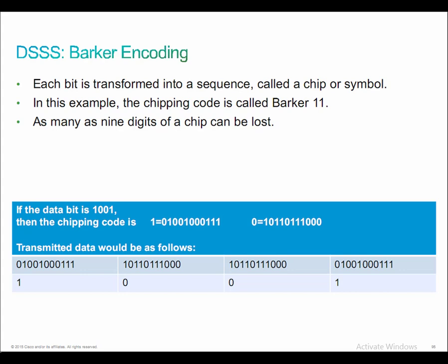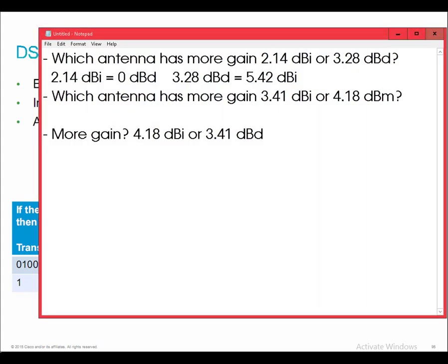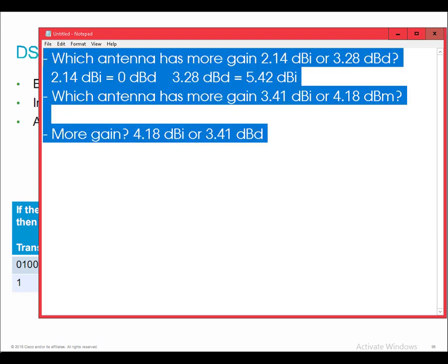Each digit of information that gets sent is run with something called an exclusive OR operation against this Barker code 11. Now, XOR operations, let me pull that up real quick. Boolean XOR operation means that if one or the other of the 2 bits being XORed is a 1, then the output is a 1.